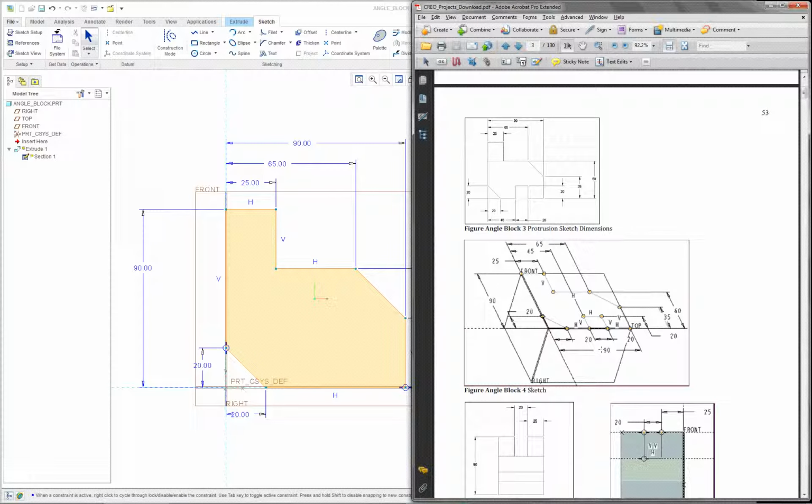The person who modeled it, and we took this screenshot for the PDF, put it all in one. Now, if an ECO comes along and your company wants to eliminate this notch, you have to go back to the very first feature and change it. And something could be referenced to it, so then you destroy your model and you have to redefine and reorganize it. And you don't want to have to do that.